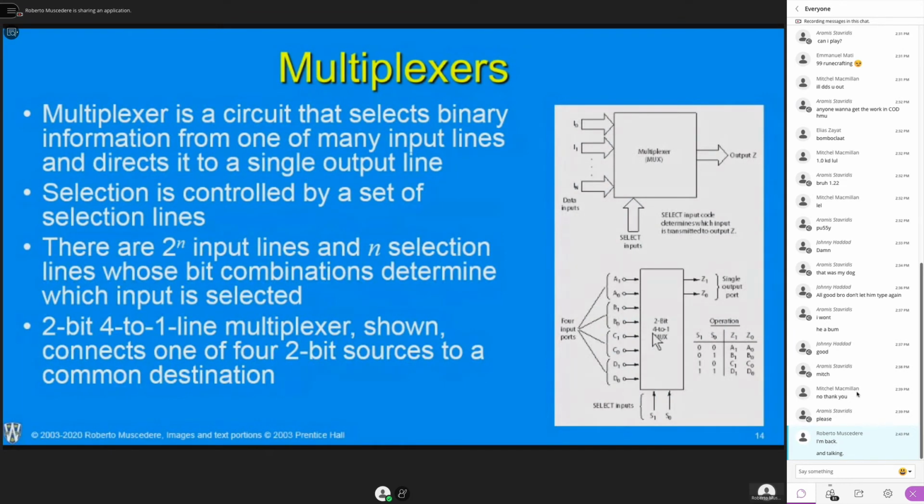Whereas tri-state gates scale well, it's only linear, but because you have one circuit taking over driving a wire as opposed to another circuit, and they don't exactly switch at the exact times, there are sometimes capacitance issues there which slow down the switching time. So we don't really use tri-state gates in high-speed design because we're trying to get the most out of the design in terms of performance, not necessarily space. So again, it depends on what our objective is.